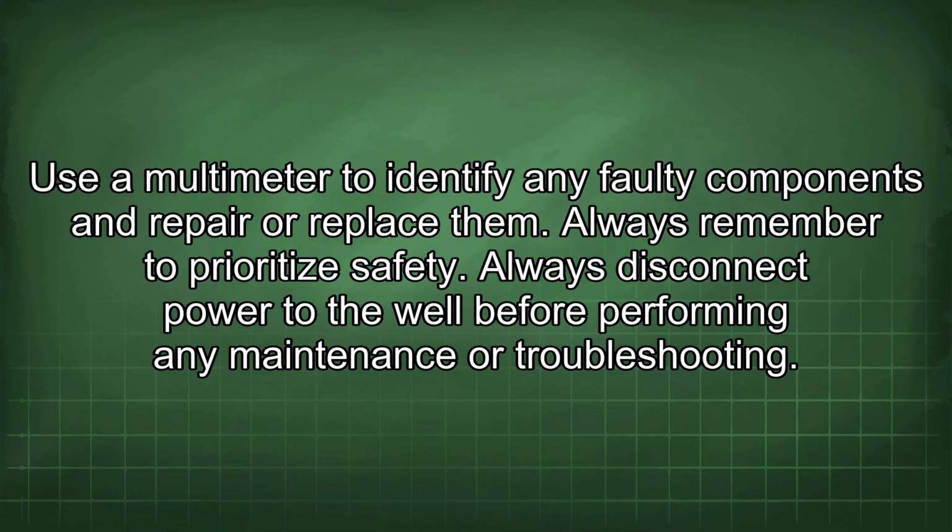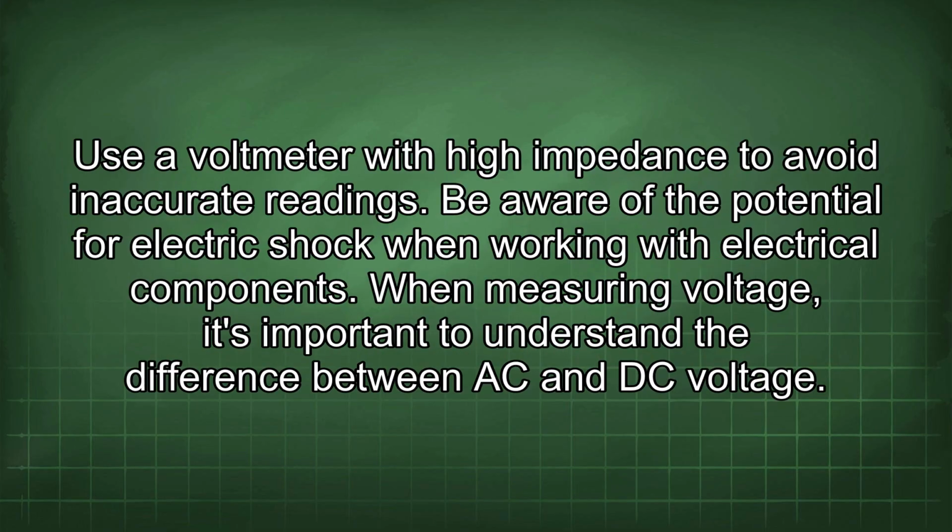Always remember to prioritize safety. Always disconnect power to the well before performing any maintenance or troubleshooting. Use a voltmeter with high impedance to avoid inaccurate readings. Be aware of the potential for electric shock when working with electrical components.